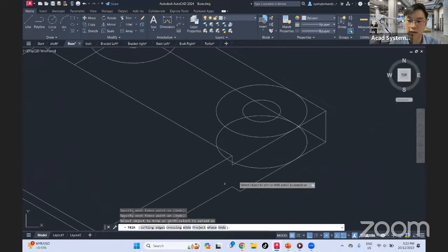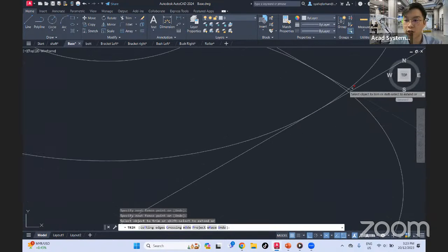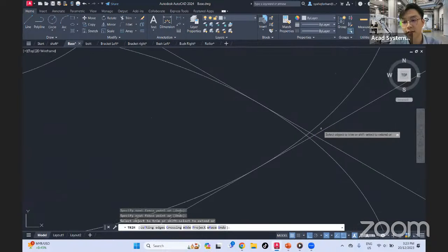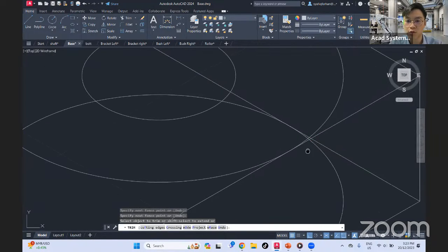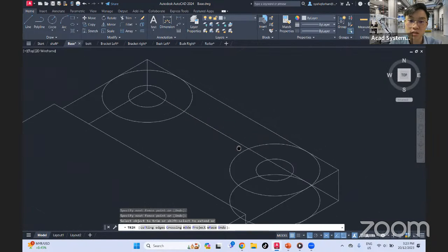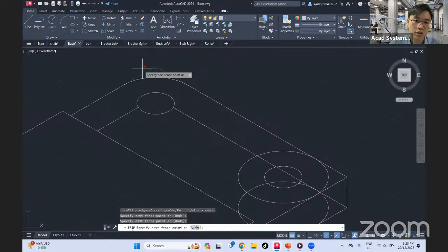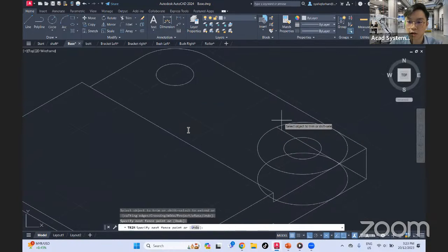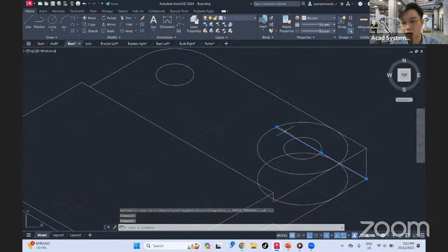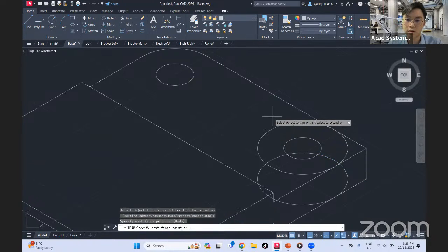Just make sure it has no small triangles, because of the way it intersects, it creates small sharp edges like just now. Same on all four corners, I'll trim it off. Or at certain points you can just use the delete function. For example, this whole line is not needed anymore. You can just click on the delete button as well. So, trim.